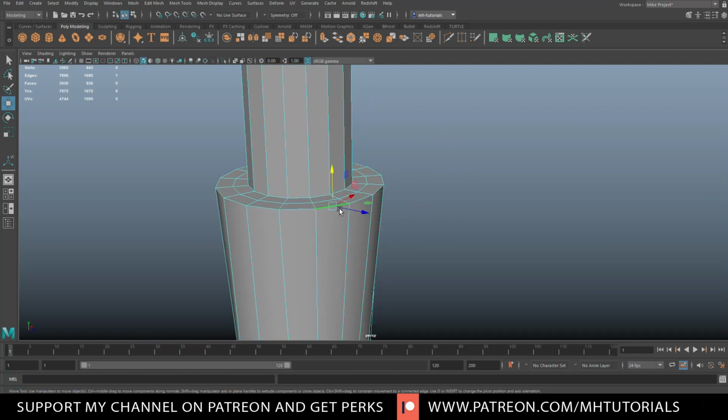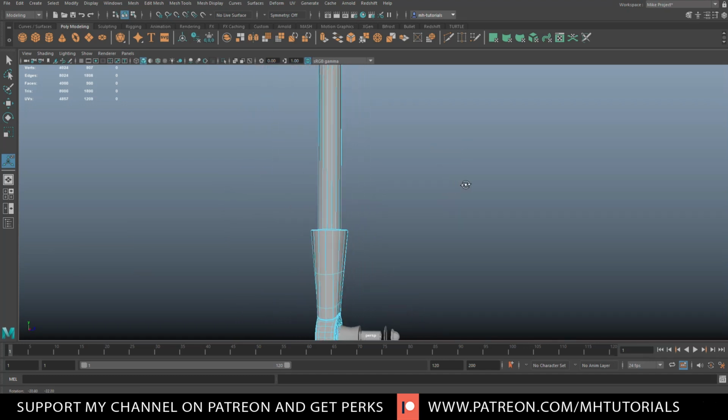We're going to get an edge, double click. And we'll actually do that here as well. And we're going to bevel that 0.01, maybe 0.04. Looks 0.2. There you go. Looks better. Okay, 2 subdivisions. There you have it. So that's good so far. Then on the top there, what we need to do is we need to bring that in, and there's going to be a threaded end there.